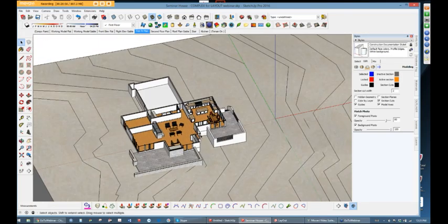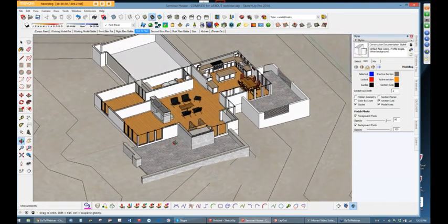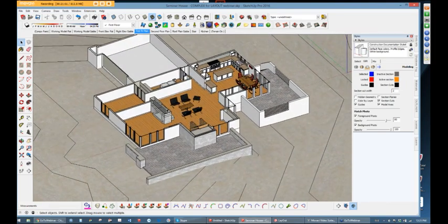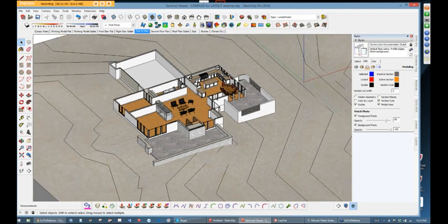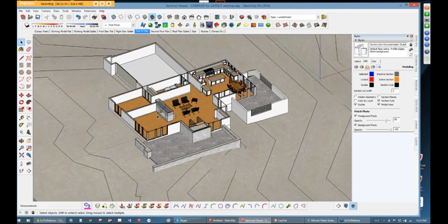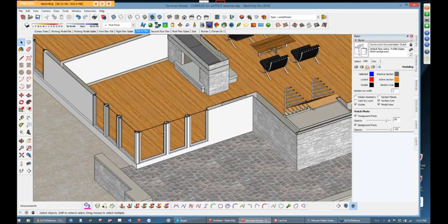That's actually a section cut. Don't fall into the trap of I'm just going to look at the model from the top. Cutting a section is much more effective because of that heavy line. And if you just look from the top of your drawing in SketchUp, you're not going to get cuts through windows. You're going to see just the top of the wall. So you won't see where these windows actually are.